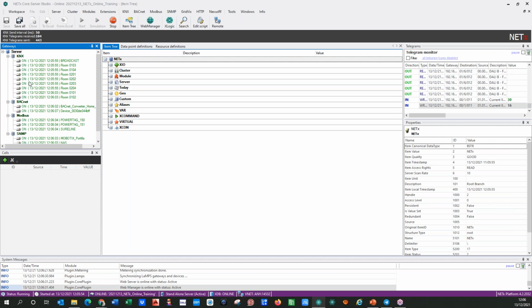We don't need expensive KNX to Modbus gateways that give you 2 problems. First is the economical problem, the money that it costs. And the second is that if you have a Modbus gateway to KNX, you will put all the traffic from Modbus into the KNX field. And this is not good because you are adding traffic that is not good for your project. In this case, the BMS is solving all these issues in one shot.